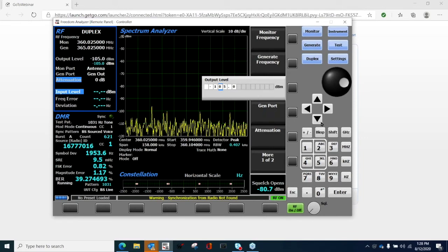In this case, what's happening? We are using the repeater on the site, and suppose you are sitting in the car close to the repeater site using external antennas on the R8100. Then you do a quick test.